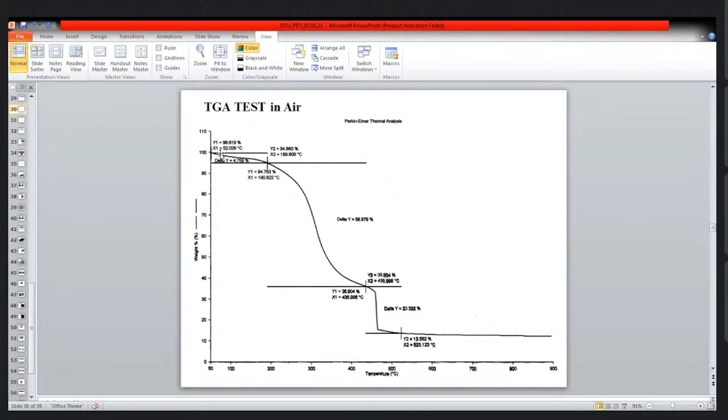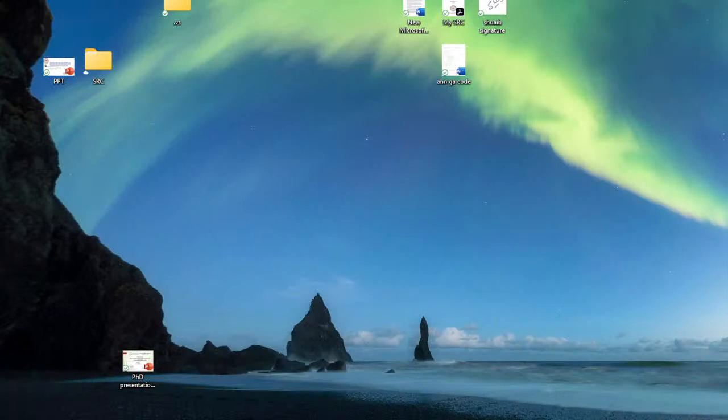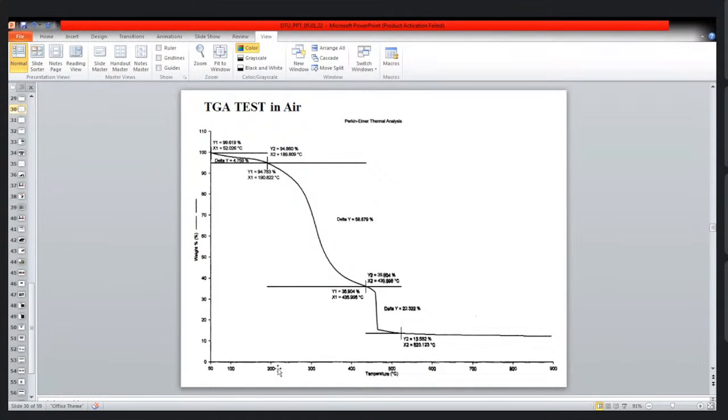So when we put the sample and start increasing the temperature, slowly the moisture is driven out, and some weight loss is observed. When the temperature becomes more than 200 degrees centigrade, between 200 to 300, the pyrolysis process will start. In the pyrolysis process, char is produced and volatile matter is released from the feedstock. And at about 450 at the most, this process will be over.